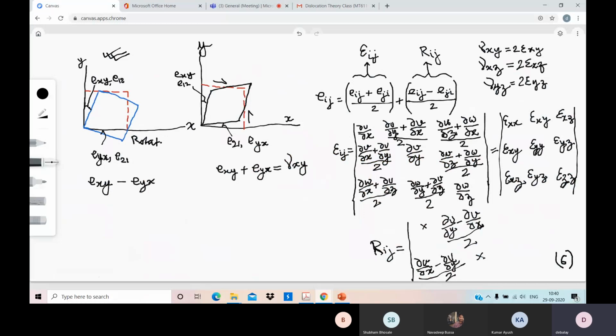Whenever there is simple rotation, you get those displacement terms because the points have displaced. So there is a displacement along this side, which is represented by EXY, along the direction X proportional to Y, or you can write it as E12.